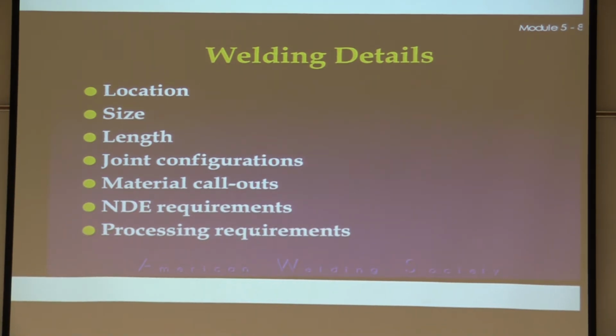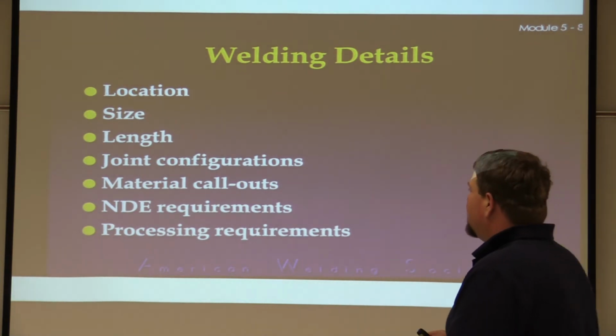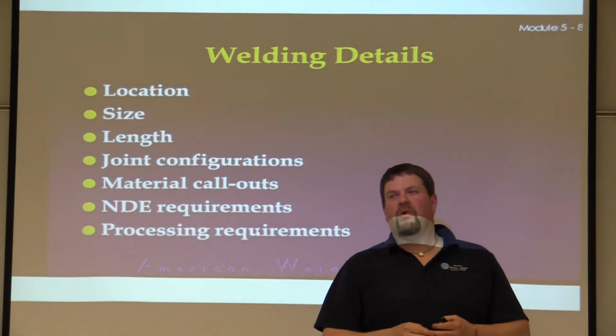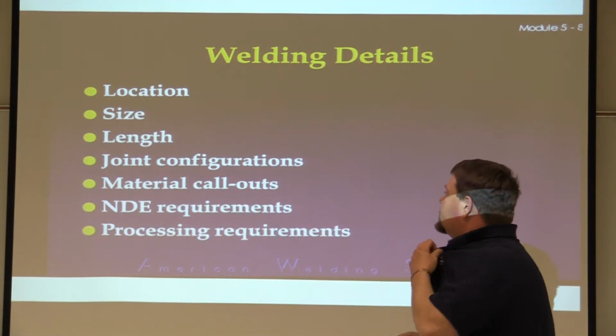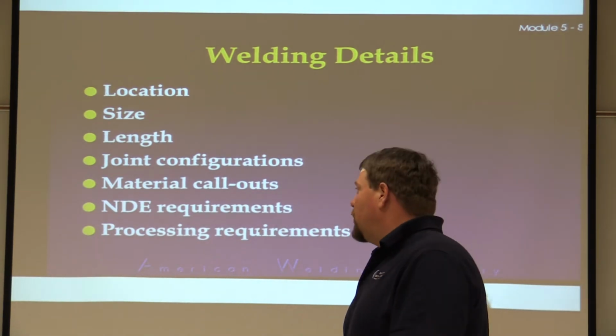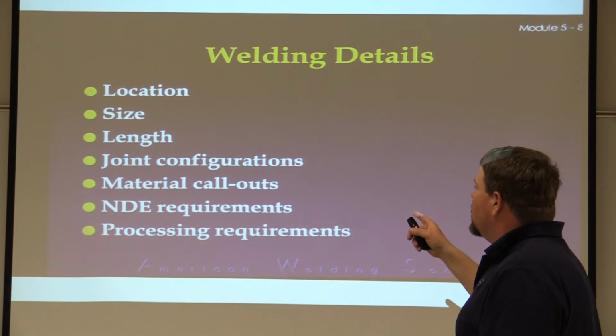Some of the applicable documents, reading off of page 5-4, left-hand column, some of the applicable documents might also dictate hold points during the fabrication process. Hold points are specific pre-arranged steps in the fab process to permit interim inspections. They can also be for material call-out. Certain materials you may have to let it cool back down before you can weld it, or it may have to have a preheat on it as well. Okay, tacked in or as welded, or preheated or post-heated also.